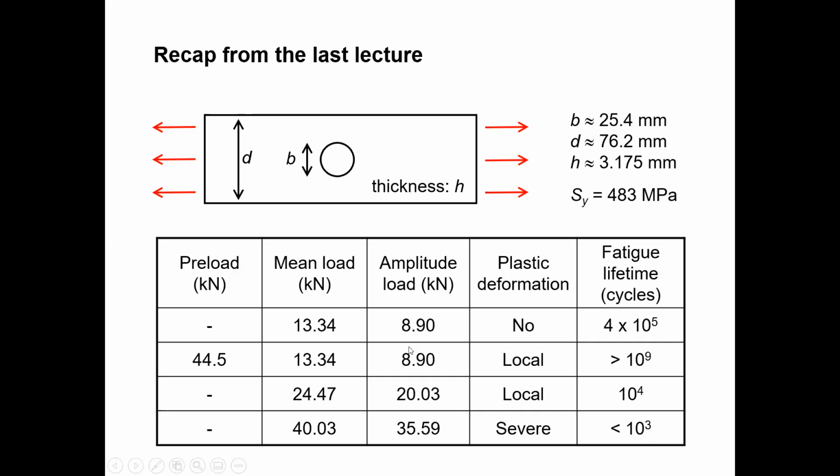You can see we calculated those values. Don't refer too much. Then you can see with this kind of stress, if you remember part B, we applied the pre-load. I told you if you apply the pre-load with one cycle, that particular material will have more strength. So even though the stress values are the same from the second cycle, there is local damage and local deformation, but the number of cycles to failure will be higher. In here, there is no plastic deformation, because the stress around the stress trace area has not reached the yield strength. With the first cycle there is a local deformation, then it will have more strength, and the number of cycles will increase.